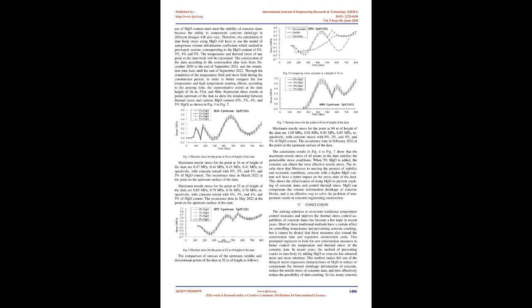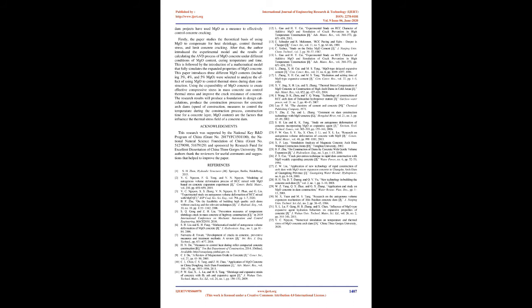Maximum tensile stress for the point at 52 m of height of the dam are 0.85 MPa, 0.79 MPa, 0.76 MPa, 0.70 MPa, respectively, with concrete mixed with 0%, 3%, 4%, and 5% of MgO content. The occurrence time in May 2022 at the point on the upstream surface of the dam. Fig. 5. Thermal stress for the point at 52 m of height of the dam.